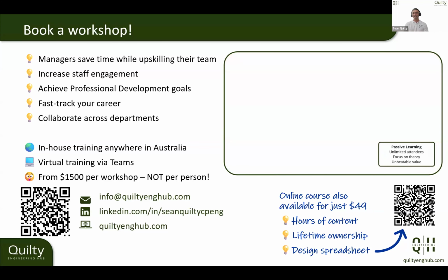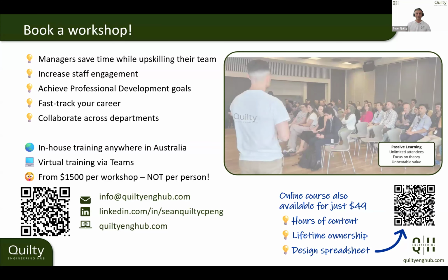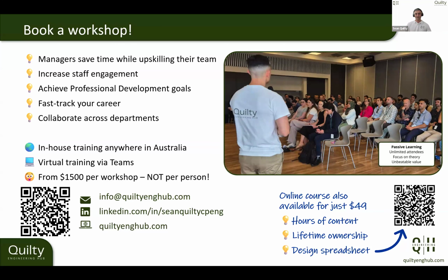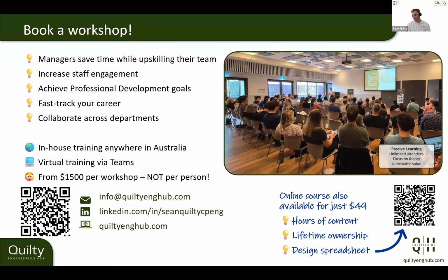But at least you don't have to rely on your pit and pipe system. And usually when you have those major events, the pit and pipe systems will fail. There'll be a blockage somewhere, there'll be overcapacity, there'll be backwater effect, all sorts of stuff will happen. So that's one really good strategy. Don't rely on really small scale infrastructure.